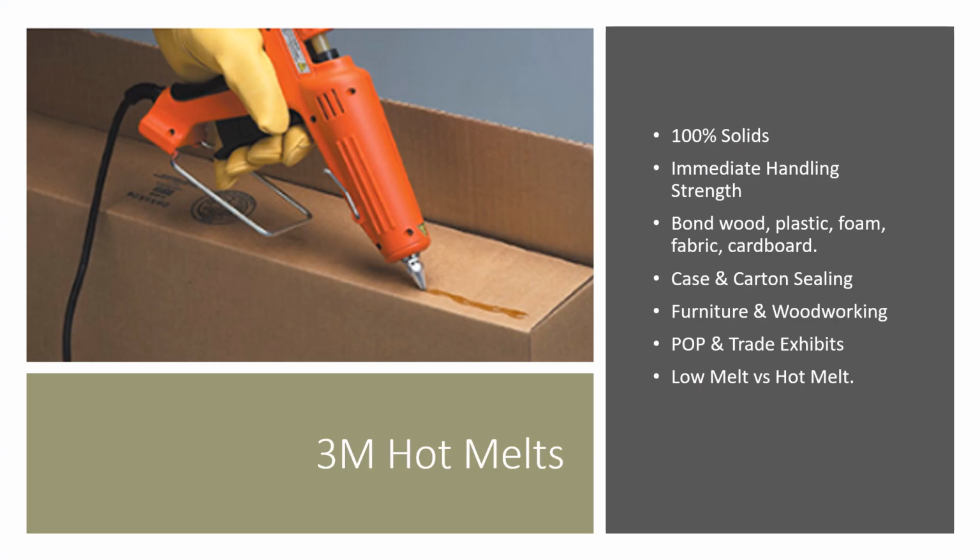3M also has hot melts, similar to the PUR, 100% solid, so no VOCs. You get immediate handling strength. Really good solution for bonding wood, plastics, foam, cardboard, light duty, lightweight materials. I've seen them very heavily used in furniture and woodworking industry on point of purchase as well.